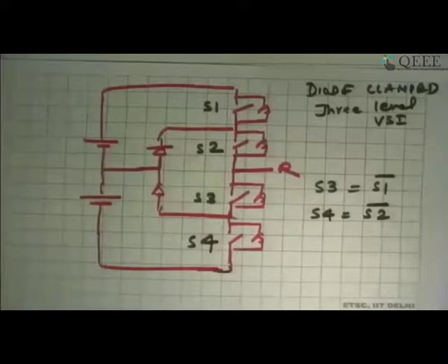So this is a very famous configuration, and most of the high power what we have from ABB or Siemens, all are 3-level. They don't work on 2-level anymore.